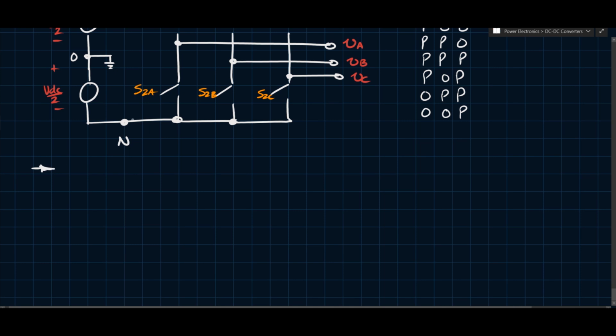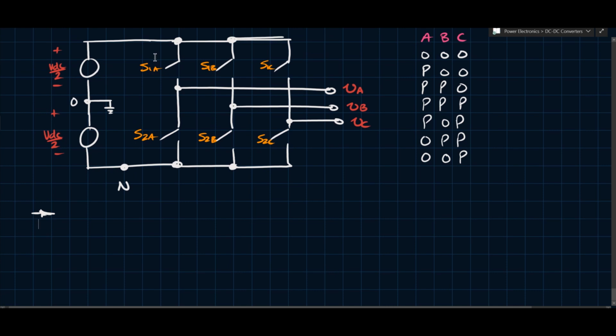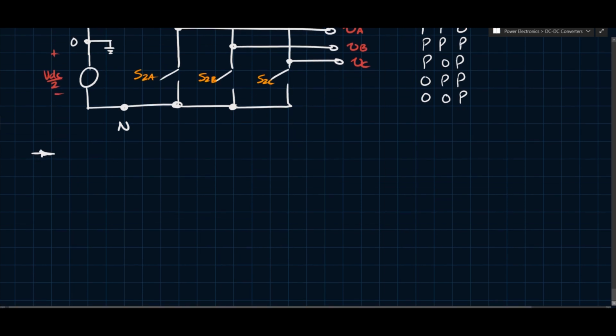But in PWM, you have basically the exact same thing as the single phase case, except instead of having a single modulating waveform, you'd have 3 modulating waveforms that are all 120 degrees phase displaced. So you would have 3 sine waves and 1 carrier. Each of these sine waves would be 120 degrees phase displaced. So this one might be 0 degrees, this one might be 120, this one would be 240. But they all compare with the exact same carrier, and they'll end up producing the required switching patterns. Still, let's look at the line to neutral.